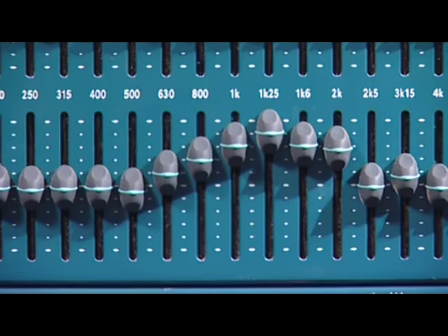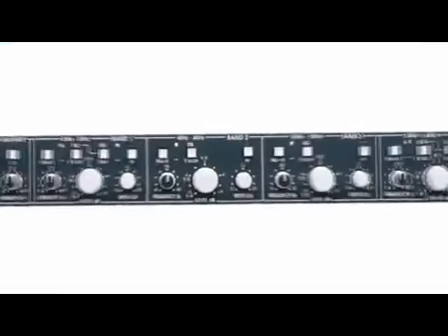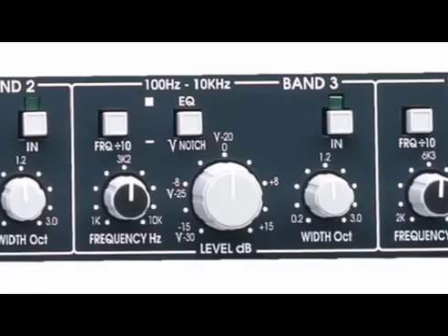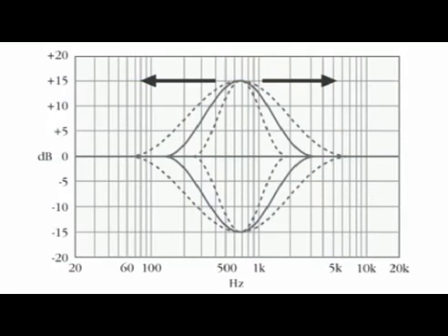Parametric equalizers are similar to the swept band EQ sections on a mixing desk, but with an important extra feature. You can vary the width of the swept frequency band. This is useful creatively and for correcting sound. You might, for example, have to fix a nasty resonance in an acoustic instrument. With a parametric EQ, you can tune the EQ exactly and narrow the frequency band until it only affects the sound you want it to.